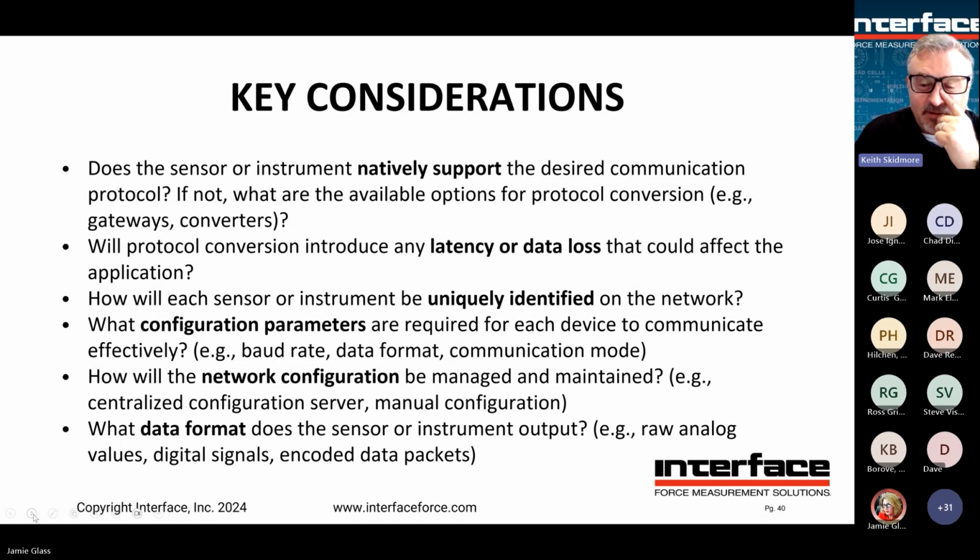How will the network configuration be managed and maintained? Is there a centralized configuration server, manual configuration? Again, do you have somebody who's an expert and willing and able to work on this? Example, say you buy a bunch of Ethernet IP stuff and you don't know that much about Ethernet IP yourself. You better have somebody on staff who does, right? And again, it's not really prudent to rely on the manufacturer to help, because typically sensor manufacturers aren't network experts. So you really do need somebody who knows the network well to set up the network side of things.